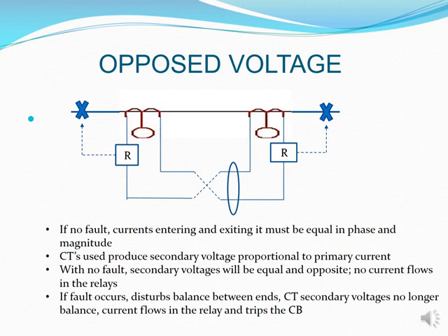And guess what? Because there are two relays, both relays will send a signal to both circuit breakers to trip, and this entire line will be out. So if on the other side of your circuit breakers there were other networks, because sometimes you have interconnected networks, then those networks will still be running and be in the system, but only this line will have been taken out of that entire system.